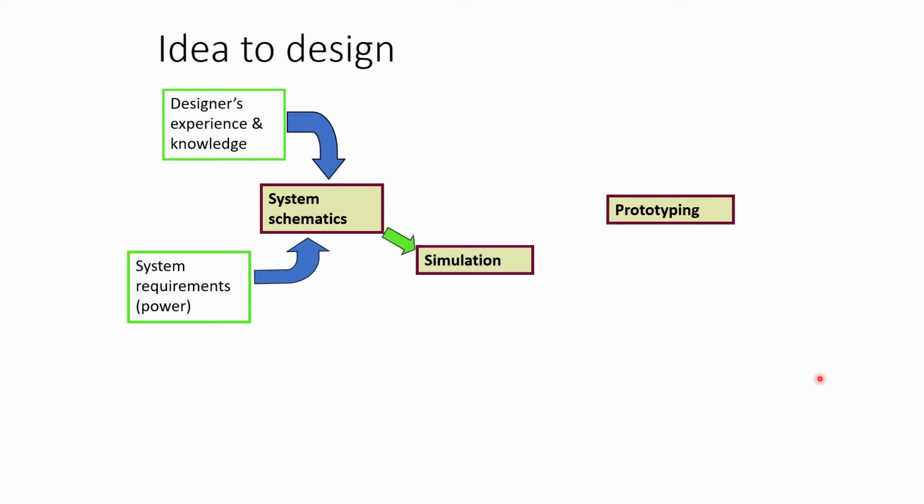If you could do the simulation using really nice software, there is a mathematical model library called PSpice. PSpice is called an engine, where you have a lot of mathematical models you can plug into different electronic components, and the engine will do the simulation and return the output. Here we also use the Spice engine, called Spice. The version ported to PC we call PSpice. So we are going to use the PSpice engine to do that.